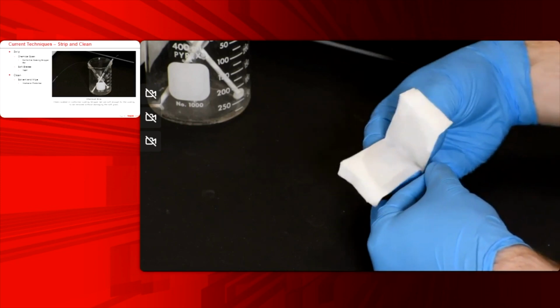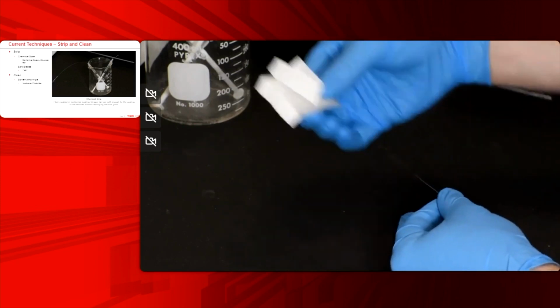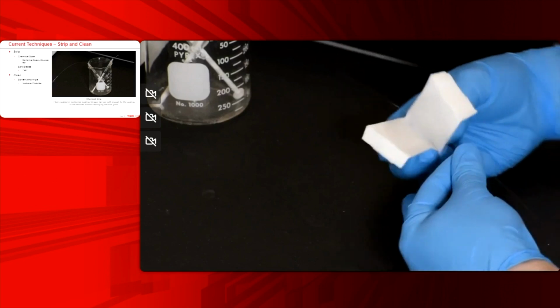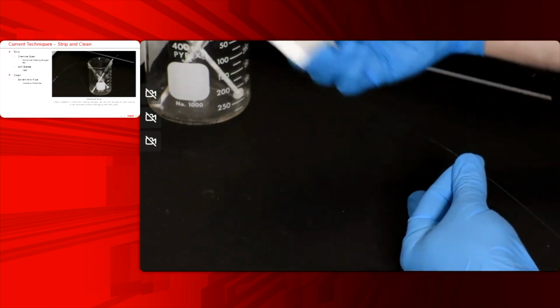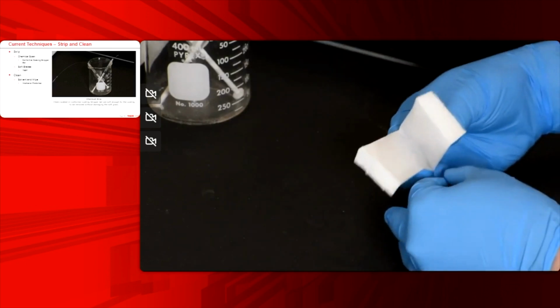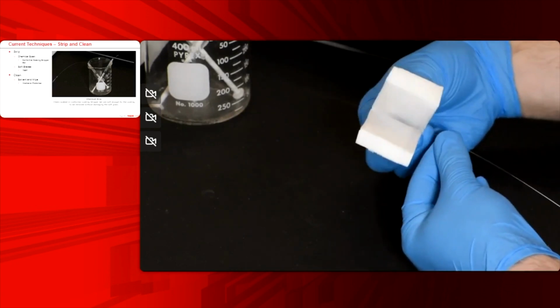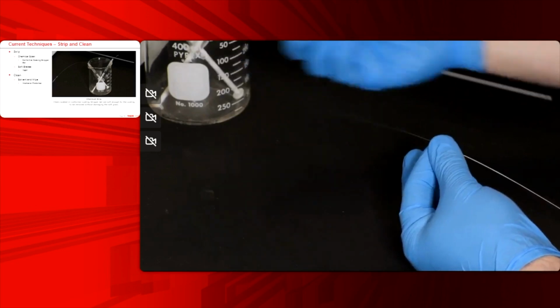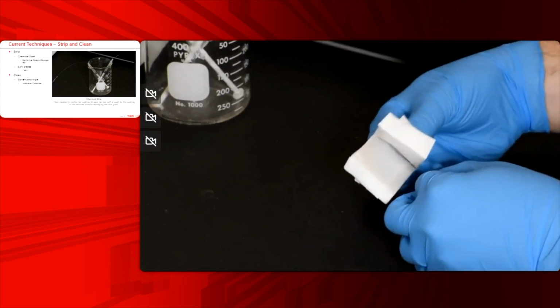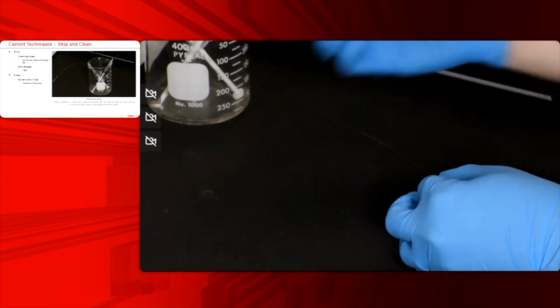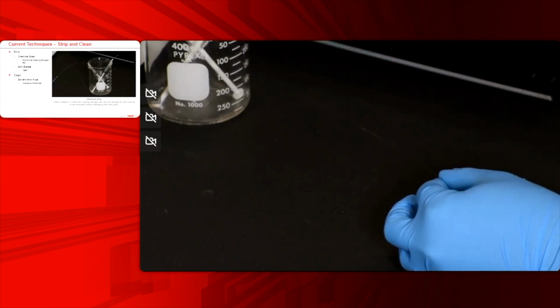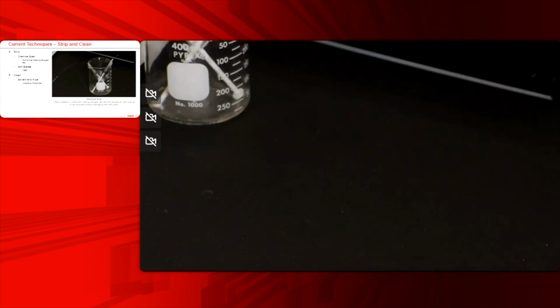Fortunately, the cleaning is very similar to silica fibers. You're just going to use a solvent-soaked wipe. Again, make sure you choose an appropriate solvent for fluoride. That might be methanol, but whatever is appropriate for the soft glass type you are using. And you're just going to pinch and wipe and even rotate the fiber to make sure you clean all around.